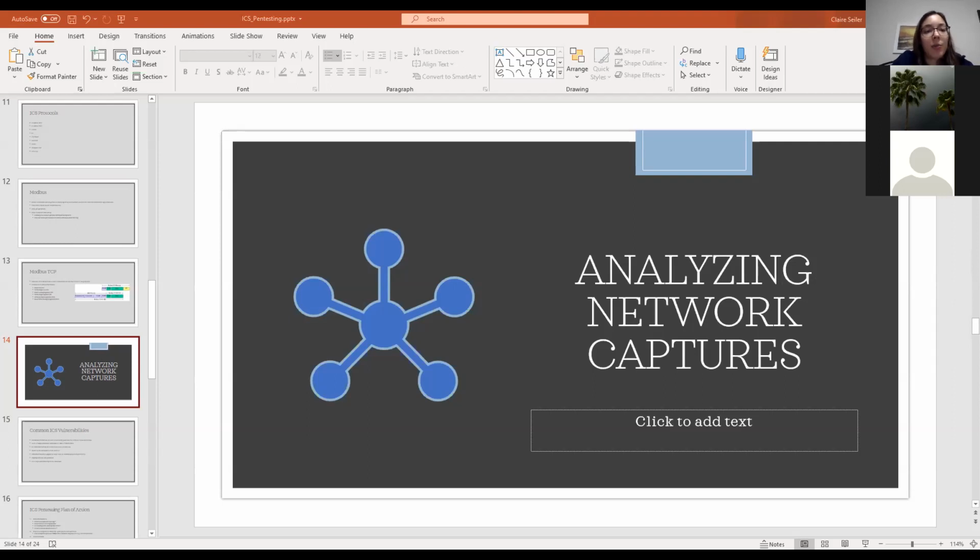So we can specifically see communication between some engineering workstation and a PLC. We see some initial communication over TCP. They're negotiating back and forth. And then we can see it switches into Modbus TCP.